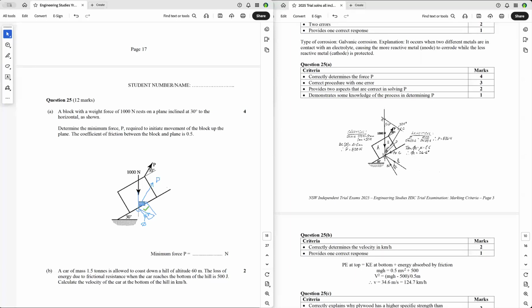And so you've got 1, 2, 3 forces acting on this body. And so we can use Bow's notation. You do your scale here. Make sure you make your scale the largest force, make it equal to between 30 and 100 millimeters, and you'll get a significantly big force diagram to make it accurate.